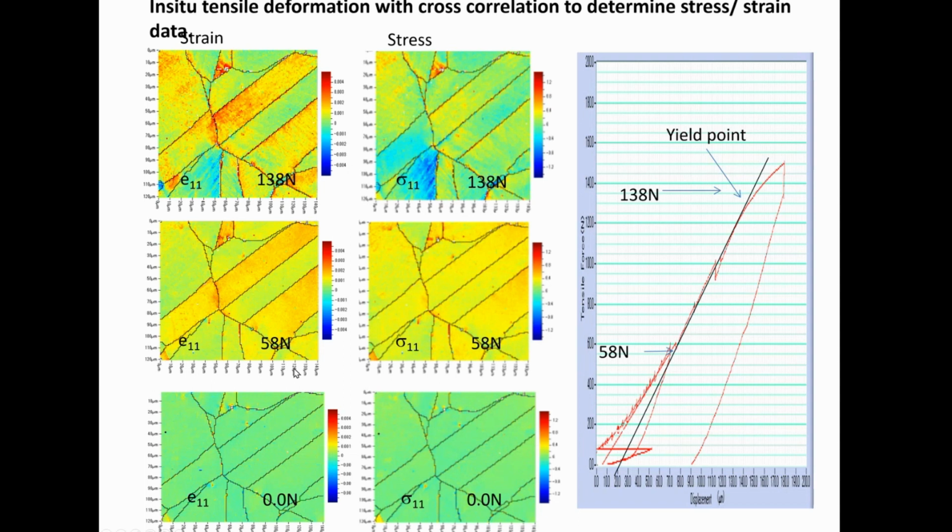But as we go up in the loading, the colors start to change, indicating a higher elastic strain in the material, until we get to this yield point, and there are distinctive zones of high strain with some straight lines in them here and here. We'll just look over here. You can see it better in the stress map here. These are the stresses residual in the specimen. These straight bands here are caused by dislocations zapping in across the grain.